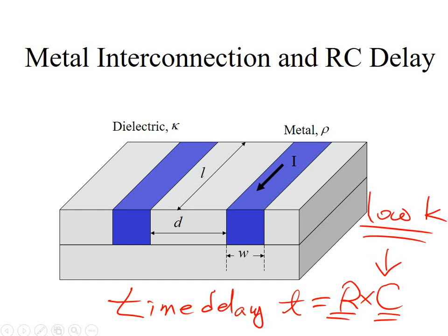The higher the dopant concentration, the higher the conductivity, which will give a smaller resistance. For a capacitor, basically you are constantly developing high K dielectric materials and low K dielectric materials, where the high K dielectric material is used for a charge storage device.